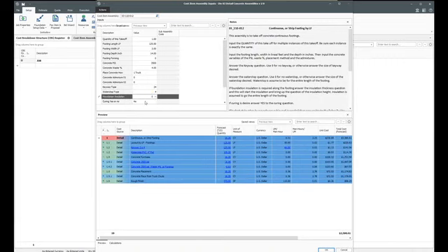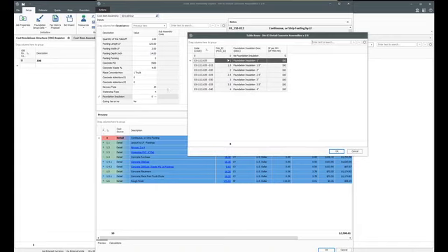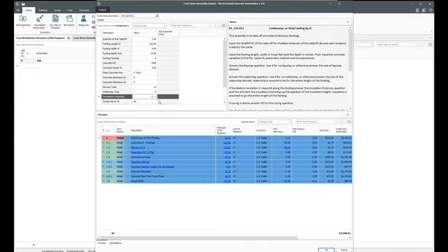Foundation insulation. I can input the type of insulation, meaning the thickness, and then it will give me questions for the depth of the insulation. If you do not want any, leave it at 0. Is there curing? Yes or no. By the way, you can change these defaults if you would like to leave curing for this assembly on all the time. These values here are calculated on these inputs up here.